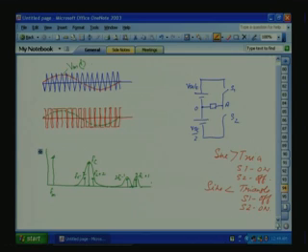So the purpose of doing the PWM is to control the output in proportion to our control voltage VMT, and also we want to shift the high amplitude harmonics to the high frequency side. So if FC is taken as 11 times FM, and FM is 50 hertz, FC will be at 550 hertz, 11 into 50, so far away.